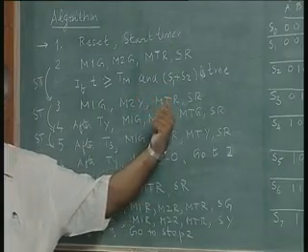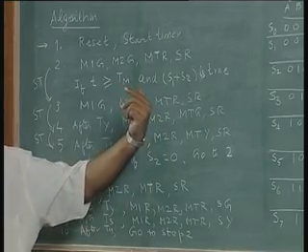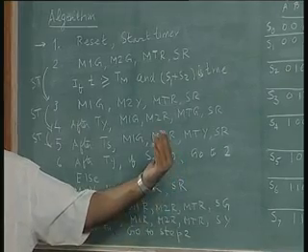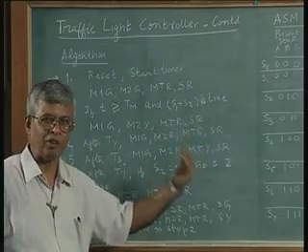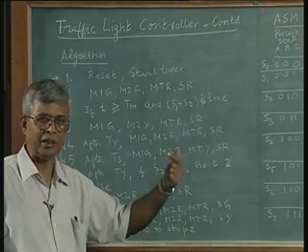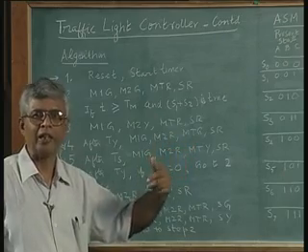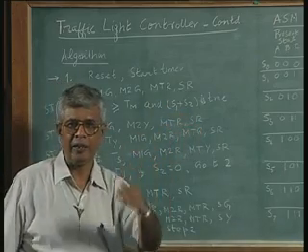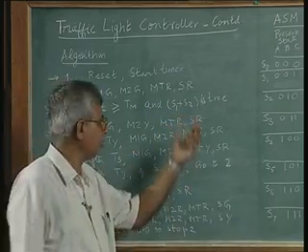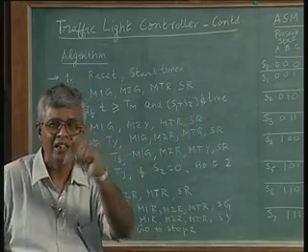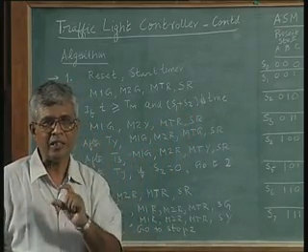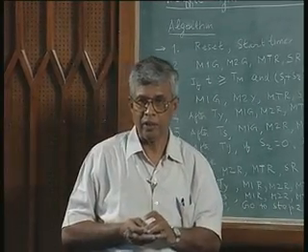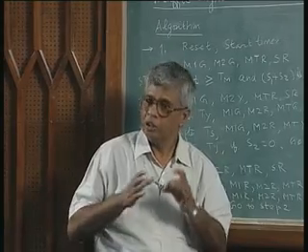First I can check S1, like we did RA RB case in the first example. We did request for bus A, request by system B for the bus. So, if RA RB was tested and then some sort of priority, here also you can do the same thing. S1 and S2 will be tested in sequence, S1 given priority, then S2, we can do that. But then each of these S1 S2 testing has to be done after every change of signal. That means the ASM becomes more complex, more number of states will be introduced, but if that is what you want, you can do it.